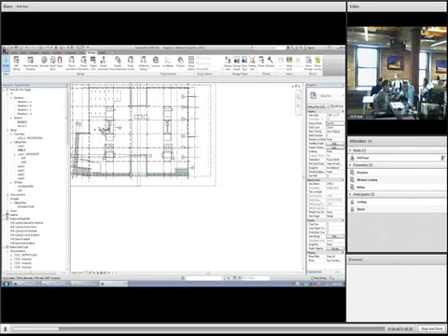Yeah, and likewise, you could still do reference planes. They are just the most flexible fixture that you can possibly use. The hosted fixtures, I think, are probably the ones that I would try to use more often, simply because you relieve that one step of having to lock the fixture. It automatically hosts to the level or the work plane or the reference plane. But even so, the reference plane would need to be locked to that level, wouldn't it? It would. You'd have to go in.